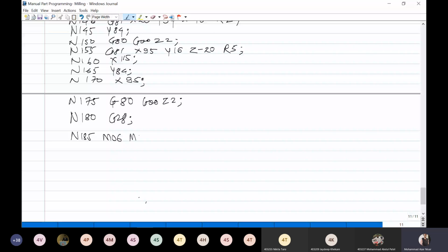First, you have to stop the spindle. I will use now 181, M05. Now we call the tool T04, and the speed, because it is a tapping operation, is increased to 300. Okay, then use 190 M03 starting the spindle.